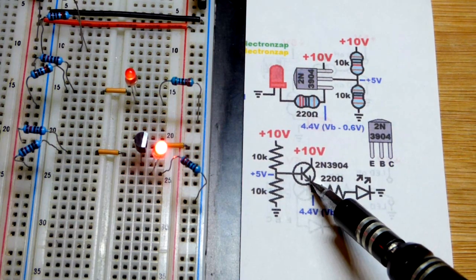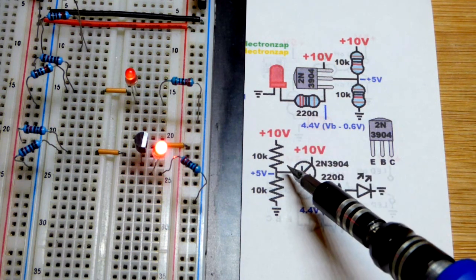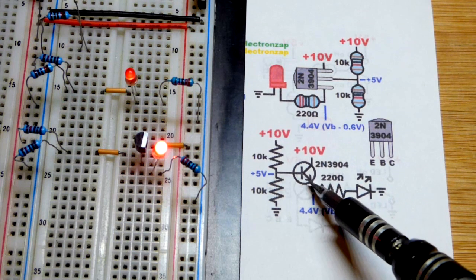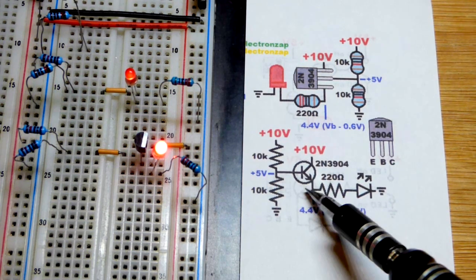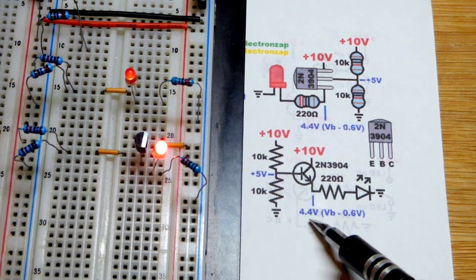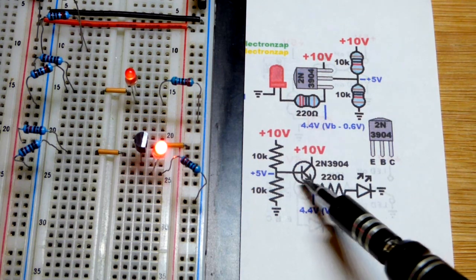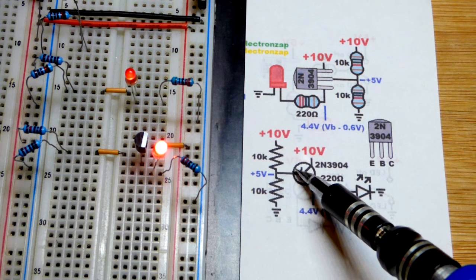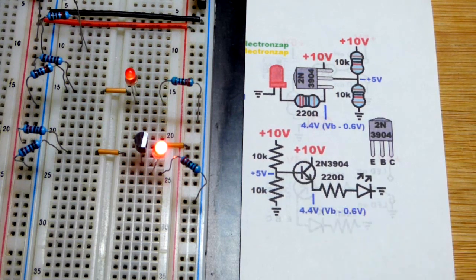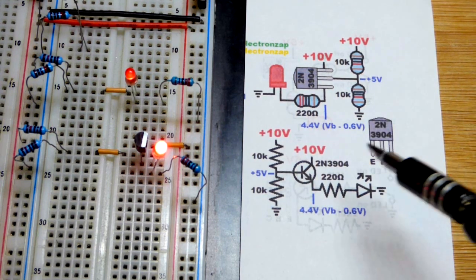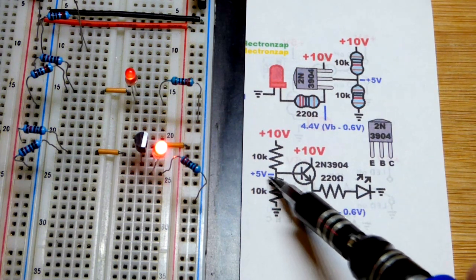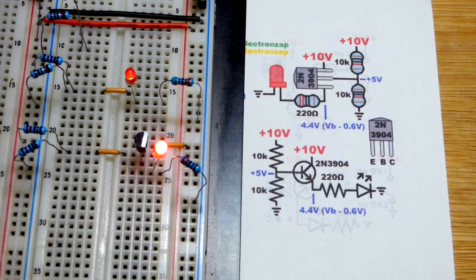And the transistor takes that tiny bit of current, lets a whole lot more current flow through, but it will only let enough current flow through to build up the voltage there, but it's minus about 0.6 volts because from base to emitter is a diode, and so you lose about 0.6, 0.7 volts from base to emitter. So in any case, we transfer that voltage minus the drop though, so since we set it to 5 volts, we're going to have about 4.4 volts.